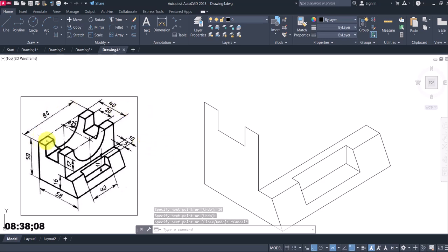All right, so now let me move to the top. Let me see what dimension I have. Let me see what information. What is this distance? The total is 80. I have a semicircle of radius 25, diameter 50. So when I subtract 50 from 80, I'm left with 30. So dividing 30 between these two sides, that's 15. So 15 here, 30 plus 50, that will give us 80. So this should be 15. All right, so distance of 15.